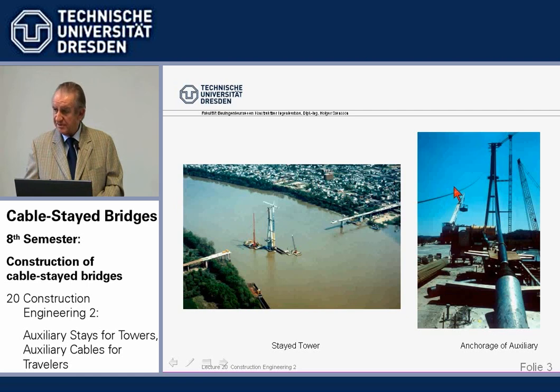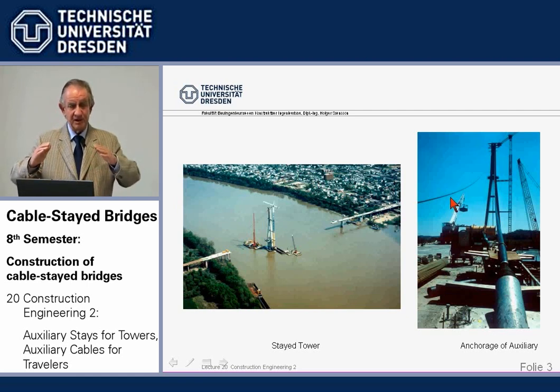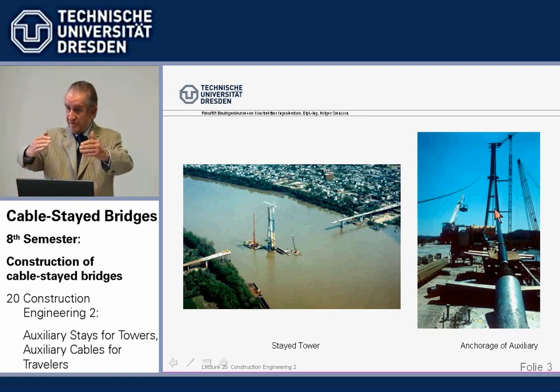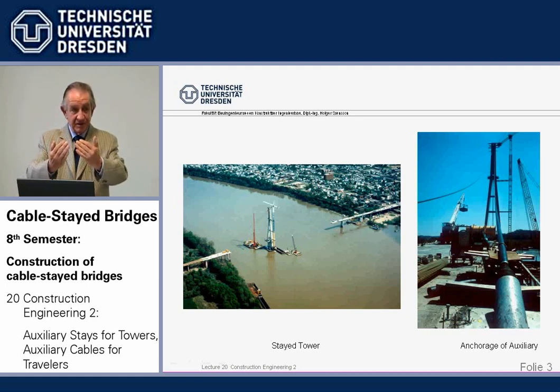and we also see a comparatively big sag, much bigger sag than in the end, which has to do with the fact that we have full stress in this cable only when we have the lifting heavy weight on a maximum lever arm on the other side. Then the slack is taken out of the cable. But when the heavy weight is on this side and the tower leans to me, then of course the cable is unloaded and we get a heavy sag.